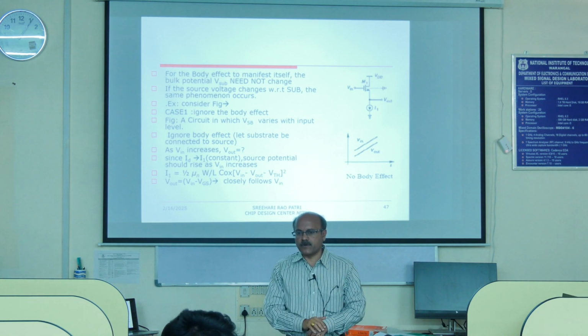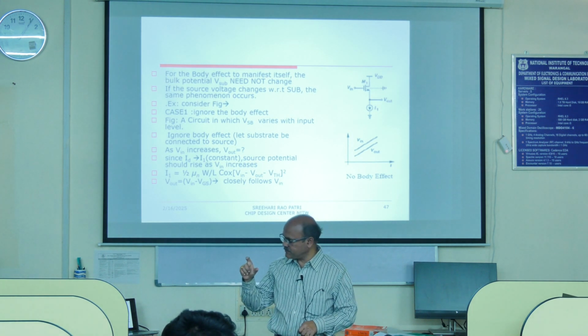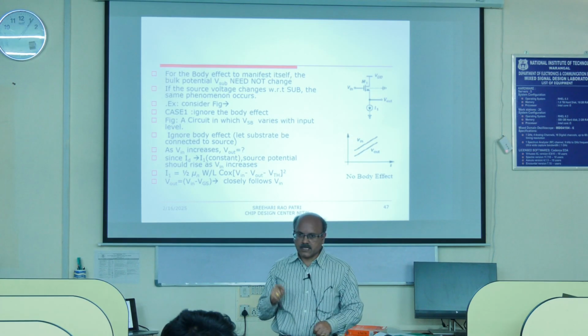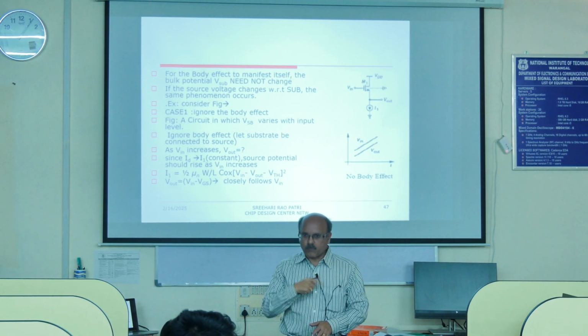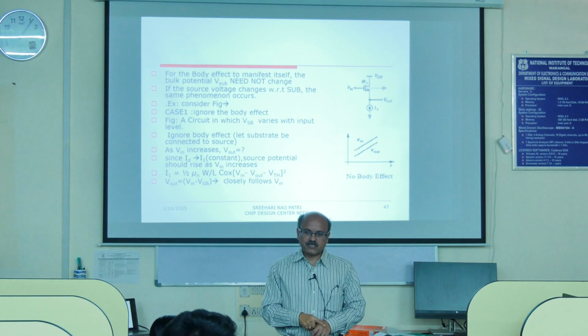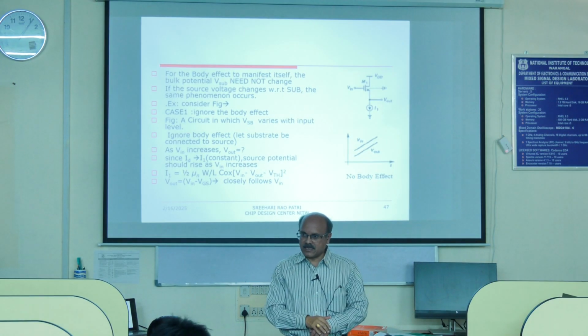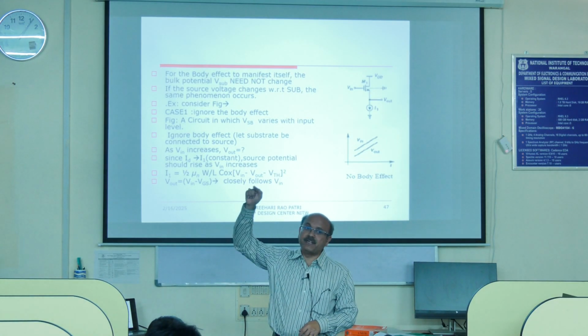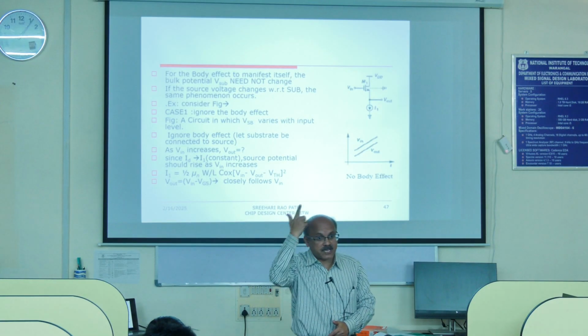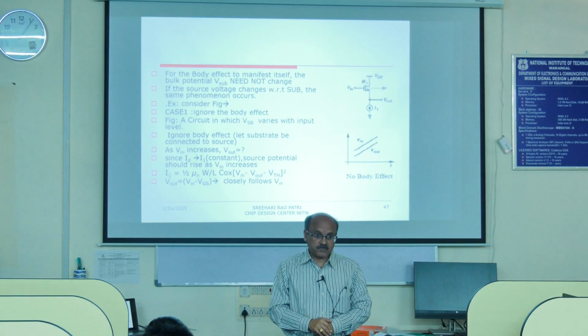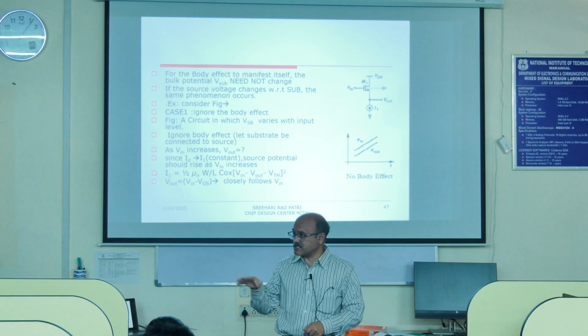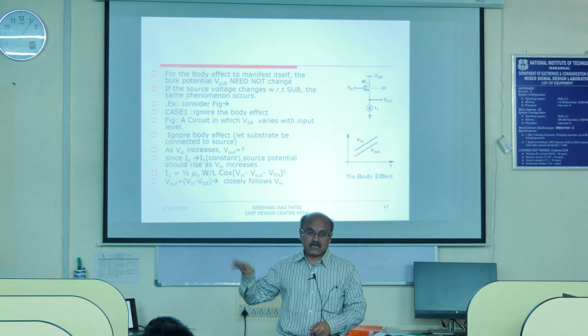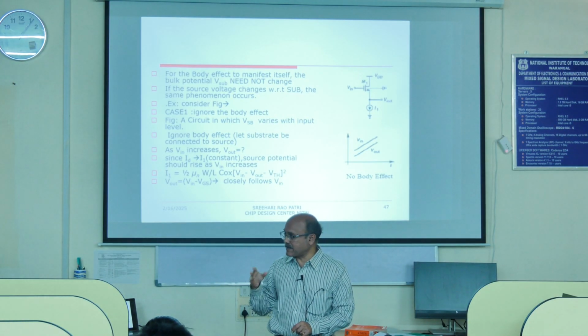So generally we prefer PMOS transistors as the loads, right? The reason being, we don't want a body bias effect. Why is there no body bias effect there? Because the substrate is connected to VDD there. You may ask me why the substrate is connected to VDD for the PMOS transistors. For the PMOS transistors, the bulk is actually N-type semiconductor.